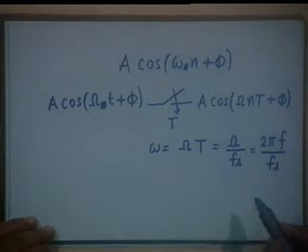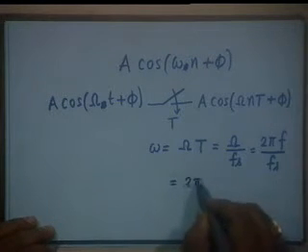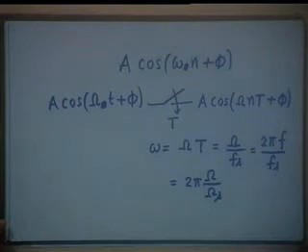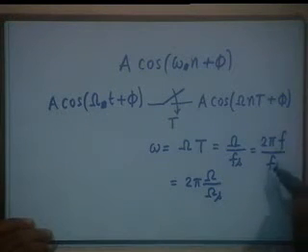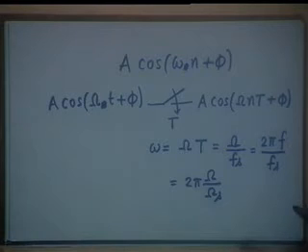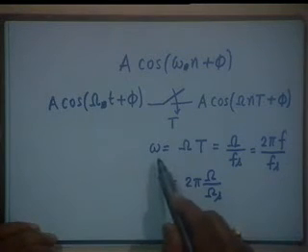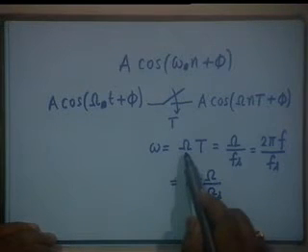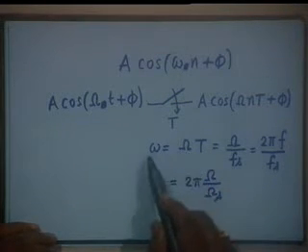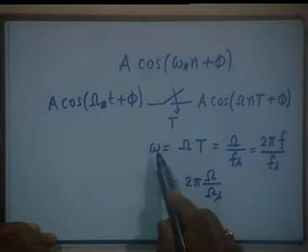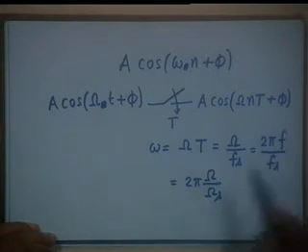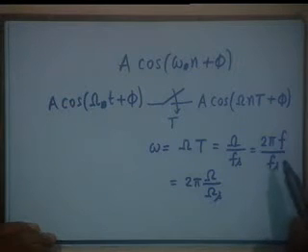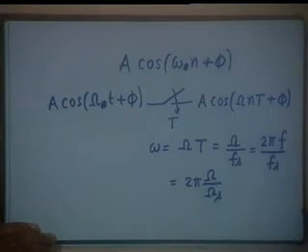And therefore you can also write this as 2 pi omega divided by omega s, a ratio of angular frequencies or a ratio of hertz frequencies, cyclic frequencies. You notice that capital omega was in radians per second, but small omega has lost its unit because F by Fs is dimensionless. Omega by omega s is dimensionless.